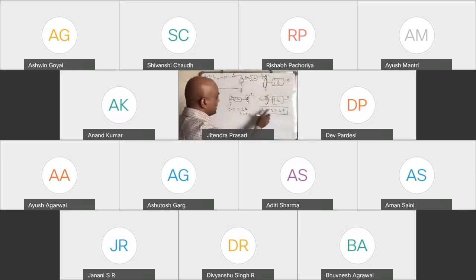So this is how both are related. So what we get here is tau minus F R1 equal to Jm theta m double dot. So this is another equation. This is F R2 equal to JL theta double dot, which is one equation. So let's call this 1 and this 2. You can see basically how they are related.